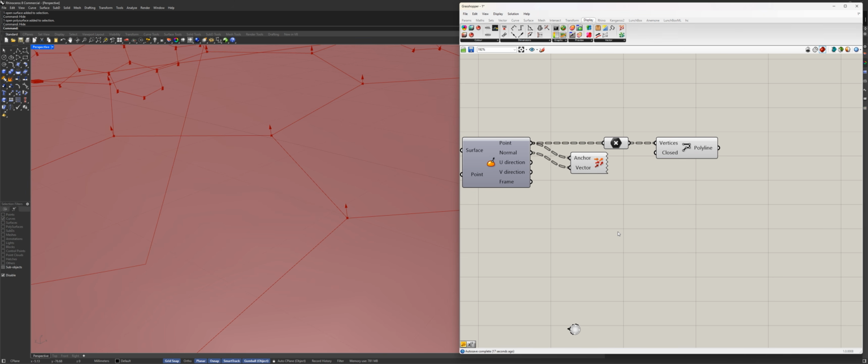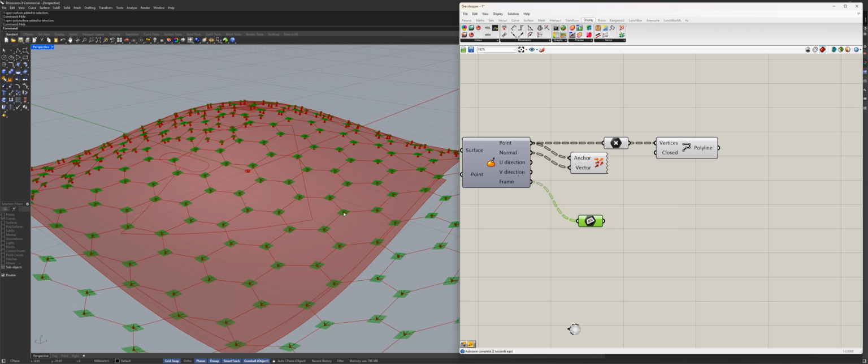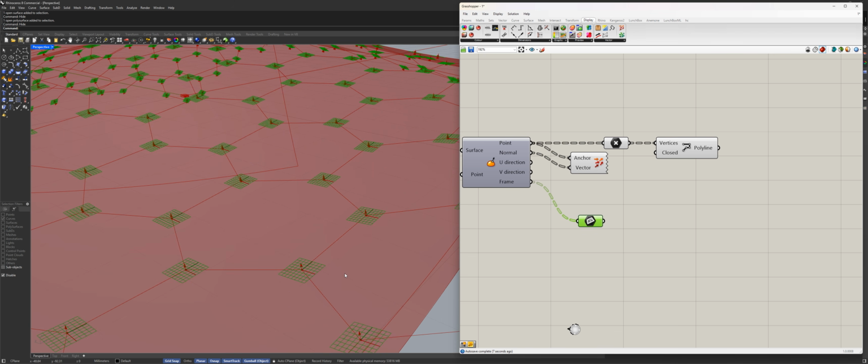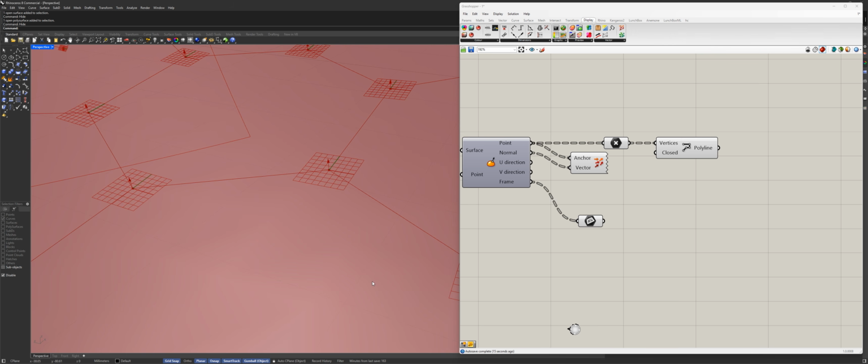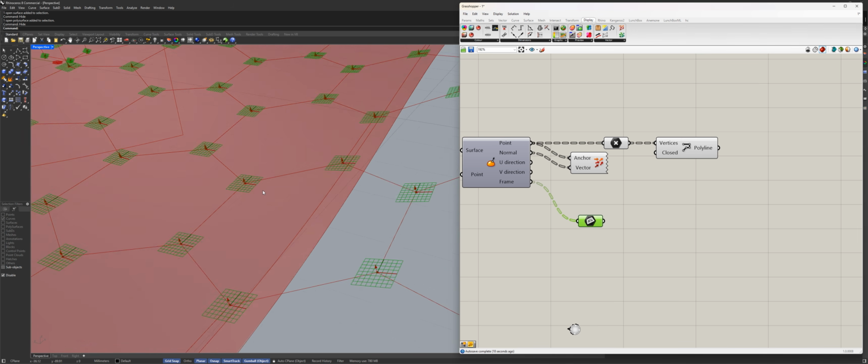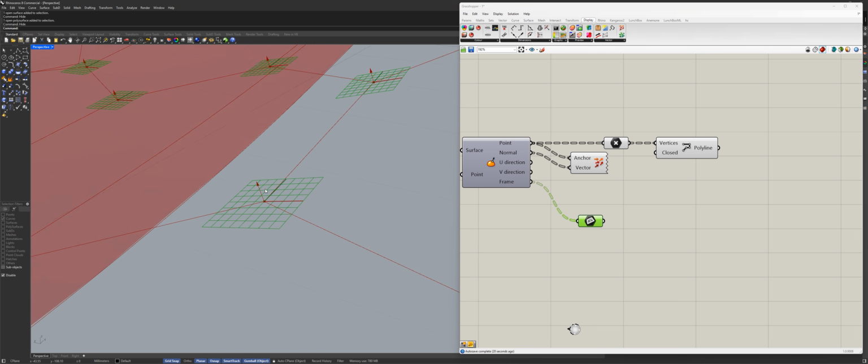Now let's look at the planes themselves, how they actually look and what they have inside. So I'll double click and I will specify that this frame is a plane. Please show me the plane, and we'll plug that in, right? And it shows me the plane. Now at this point, your planes may be huge or maybe very small, and you can't see anything. Let's go to the display, preview plane size, and set the value. Mine is set to 4 right now, right? So they're not very big, not very small. So this is a plane, or its visual representation, right?